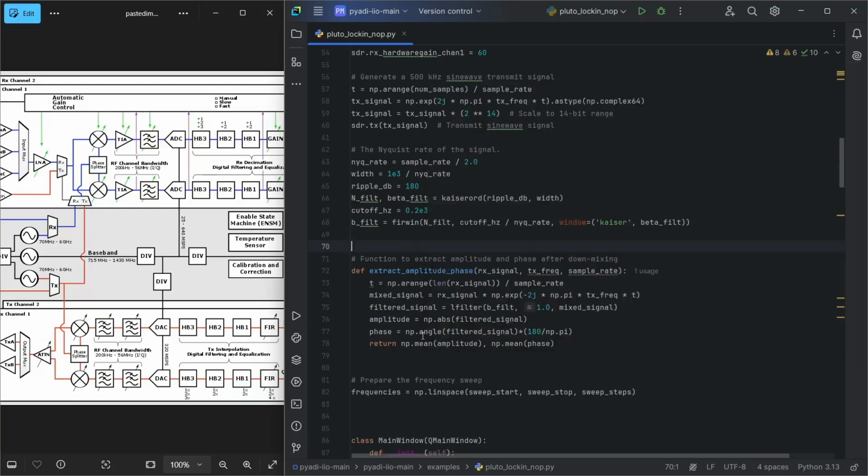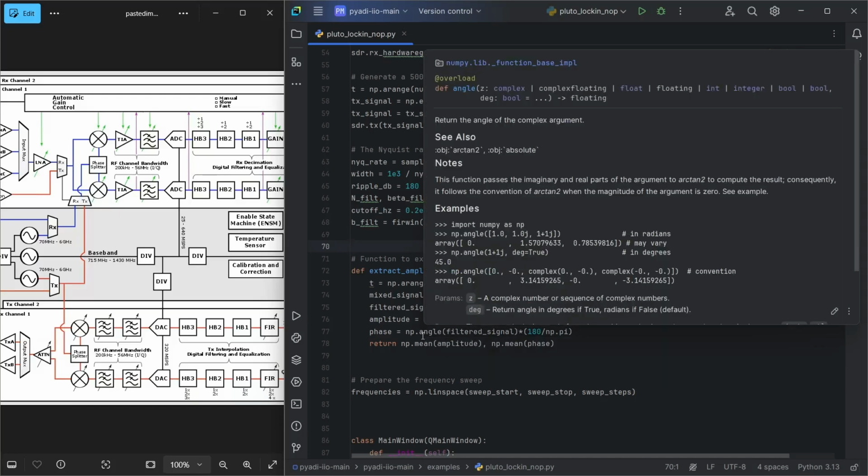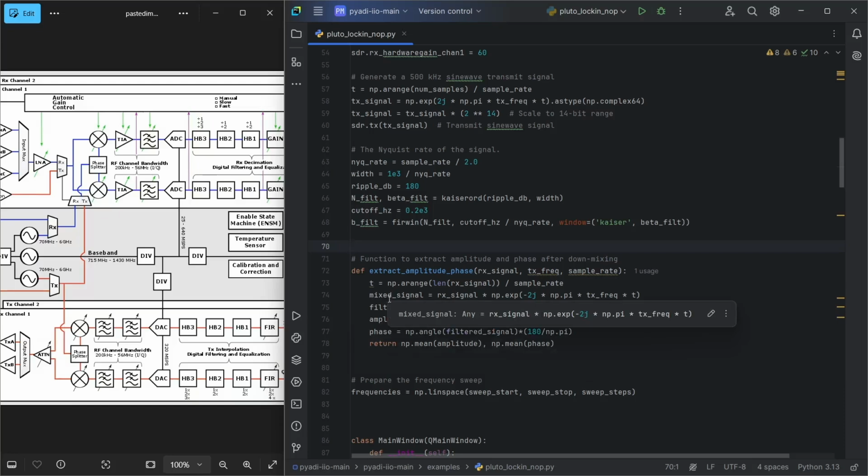Let's assume that we send a signal, then by SDR.RX we read the ADC data, which means the time that we read the ADC data is just some arbitrary time based on when in our Python we read back the ADC output. What happens in this scenario is that the exact timing of when we read back the ADC data may not be aligned to the exact time that this sine tone, which is generated here with phase 0, is received here.